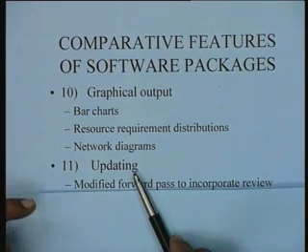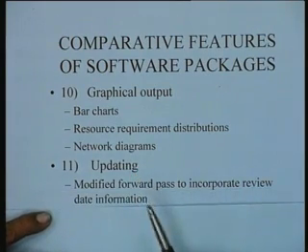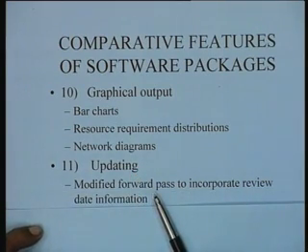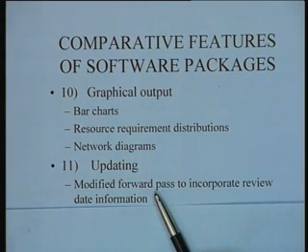So what does updating really mean? In a physical sense, if I review my project on a certain date, I have to compute the remaining durations for the various activities. Activities which have been accomplished, their remaining duration is 0.